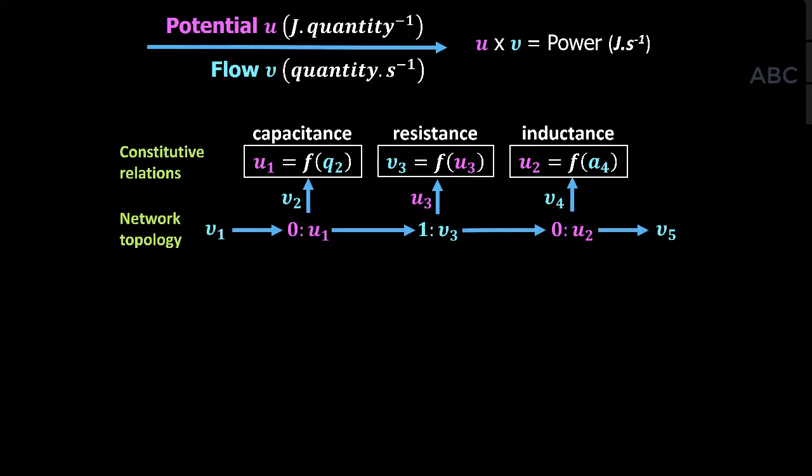And then all of them, of course, you're going to be dissipating energy, turning it into the entropy of the universe around. And so you need the ability to define a relationship between flow and potential that represents that dissipation. And in all of these white boxes where we're defining storage or dissipation, we're dealing with constitutive relations. That is, they're black boxes, despite being shown as white.